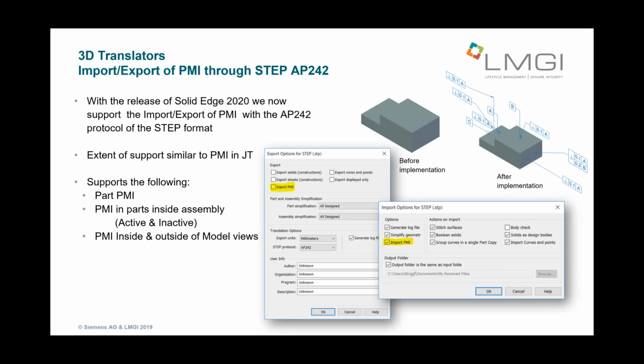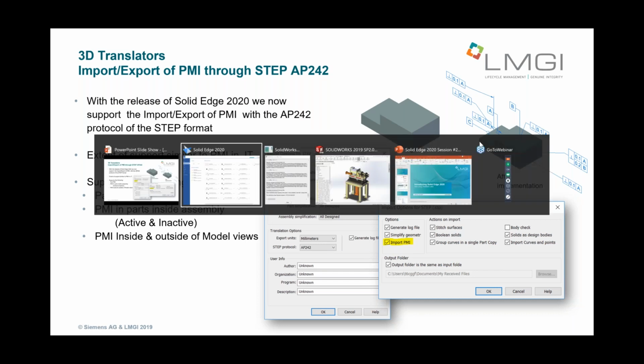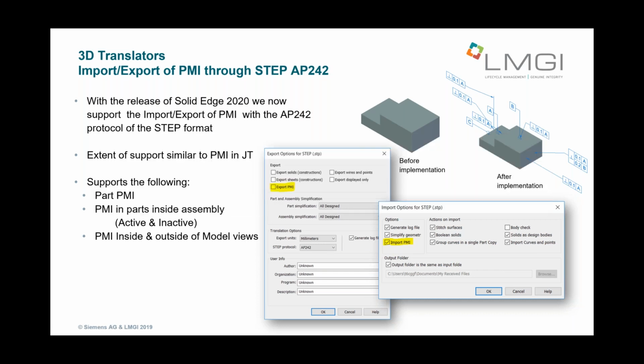There is another file export. I thought this might be on topic since we are talking about importing and exporting data. When you save a STEP file, something that's been added in the STEP AP 242 standard is the ability to put PMI data out. Product manufacturing information data can now go out into the STEP file. Let's take a look at a couple of these just as examples.